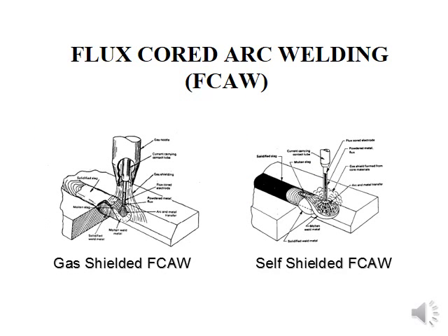The flux-cored arc welding process, also known as FCAW, uses a tubular electrode wire filled with flux. The arc established between the electrode wire and the base metal, as in all arc welding processes, provides the heat for welding. There are two variations. One using auxiliary shielding gas from an external source, the other with self-shielding. The core of the tubular electrode contains fluxing, deoxidizing, and at times alloying additions. The molten slag that floats on the liquid weld metal provides physical protection from atmospheric contamination.